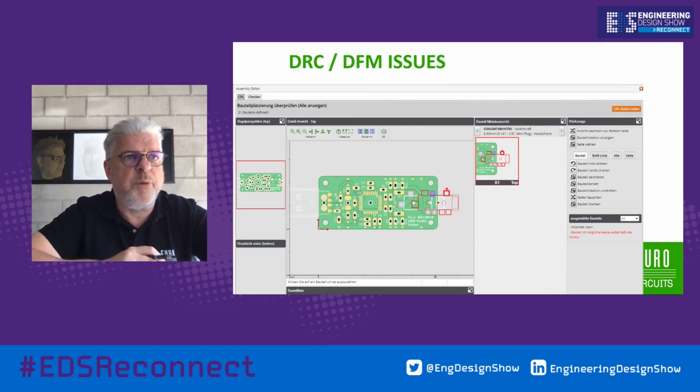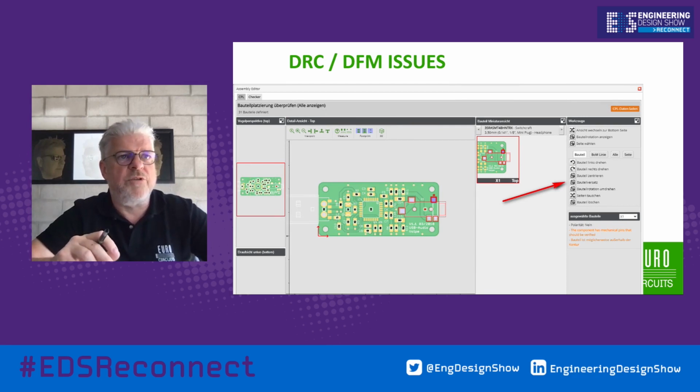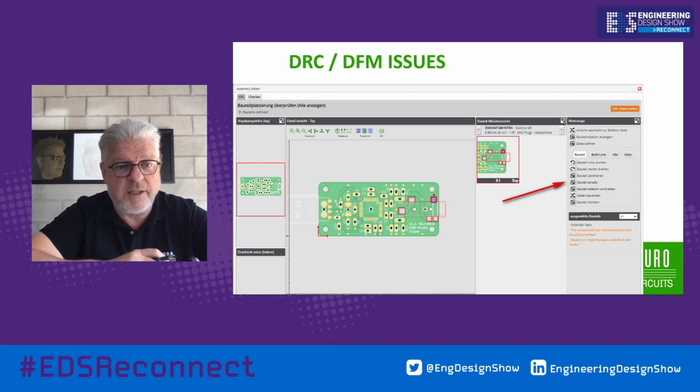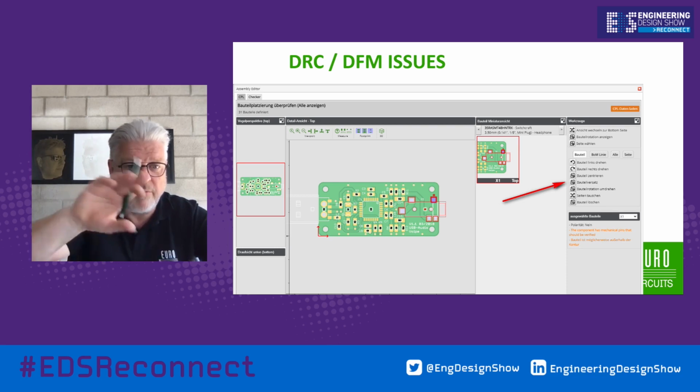Aligning the components on the PCB is important for checking, but it's later on also important for us. If we do the assembly, then our operators are doing this in the work preparation for the assembly. But if you want to make absolutely sure that your component fits, it's definitely something that you can check before order as well. And also check if the rotation of the component is clear for everybody, especially with symmetrical components. Is it clear which is pin 1 on the component, and are they at the same rotation?